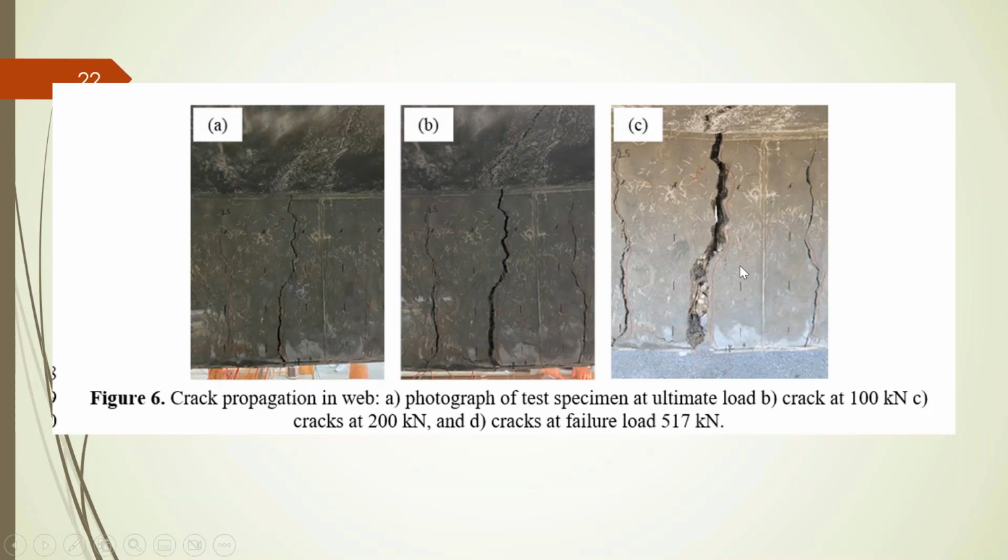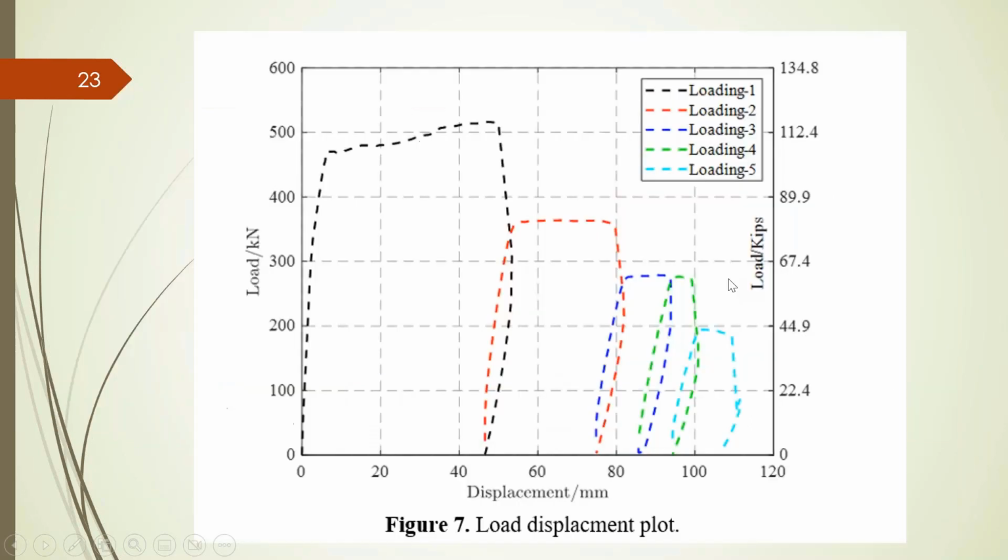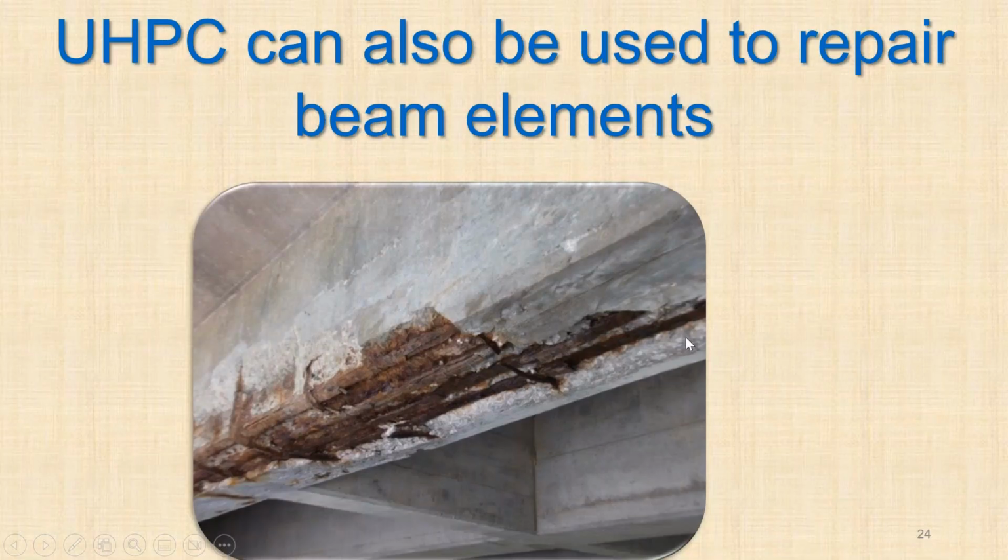We did get distributed cracks, very large deflection, and basically here is a load deflection. What you are seeing over here is basically the rupture of the first layer of the reinforcement close to the bottom surface, and then the next one, and so on. So this was the load deflection response of the beam.